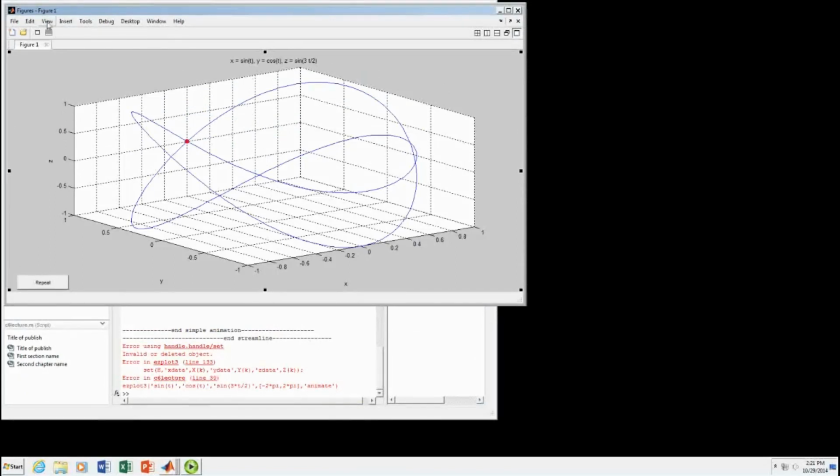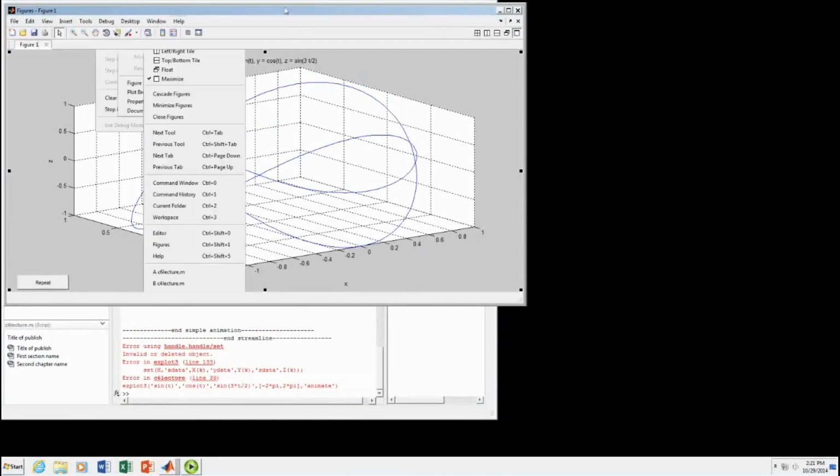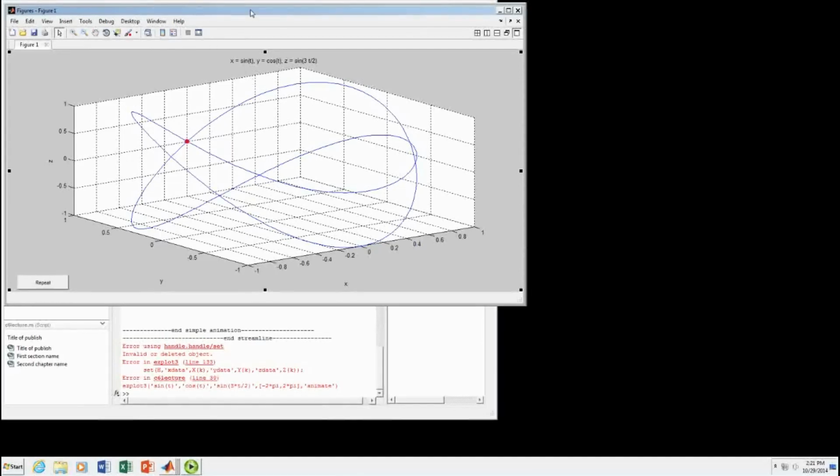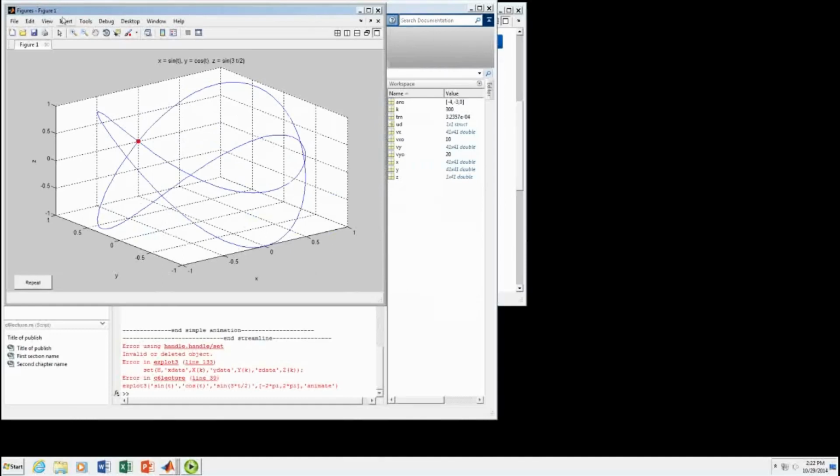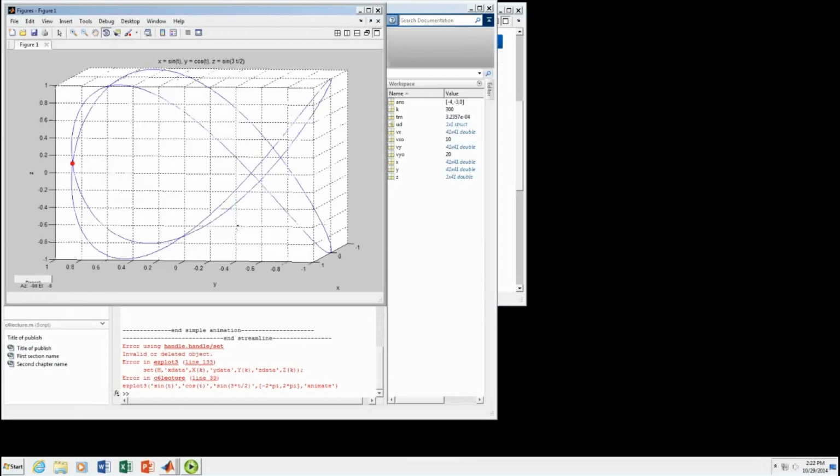Figure toolbar there. View. There, that's the one I wanted. And get out of it. Let's see, get out of the select. There, get out of the select. Let's change the size again to a more reasonable size. I can rotate. Now, I had to go to the figure toolbar, which brings all this section up. If I get rid of the figure toolbar, it just gets rid of it. Now it puts all these commands, including the rotation command, so I can change it around.